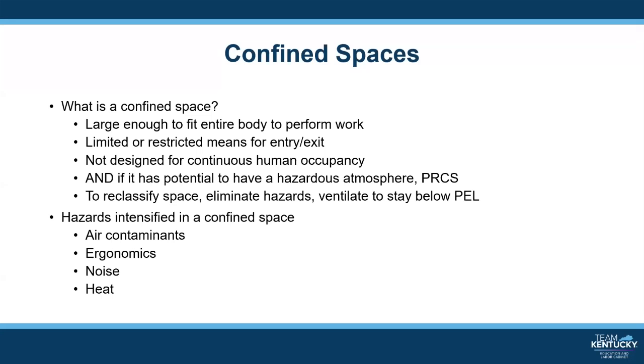For example, oxyacetylene cutters and hoses must be removed and or at least separated from the gas feed during these breaks. When welding in a confined space, the air quality is particularly important. Management must ensure that the entire space contains healthy, breathable air at all times.